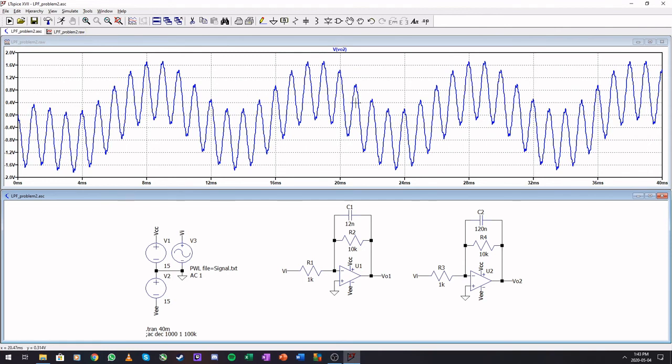And you can see that most of the 100 hertz is there, but there is still a little bit of 1K left. And if you look at the points here, a little bit of 10K remains. Okay, so if you want to get rid of some of these components much better, you need to go to higher order filters. But we can see that the elements have been removed.